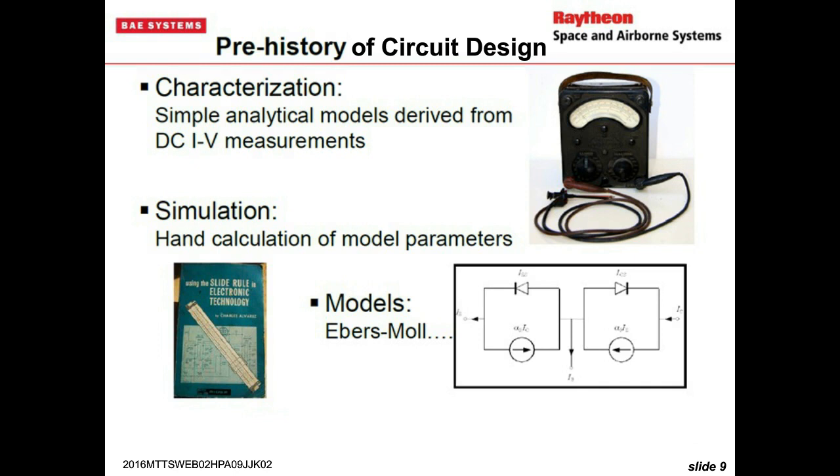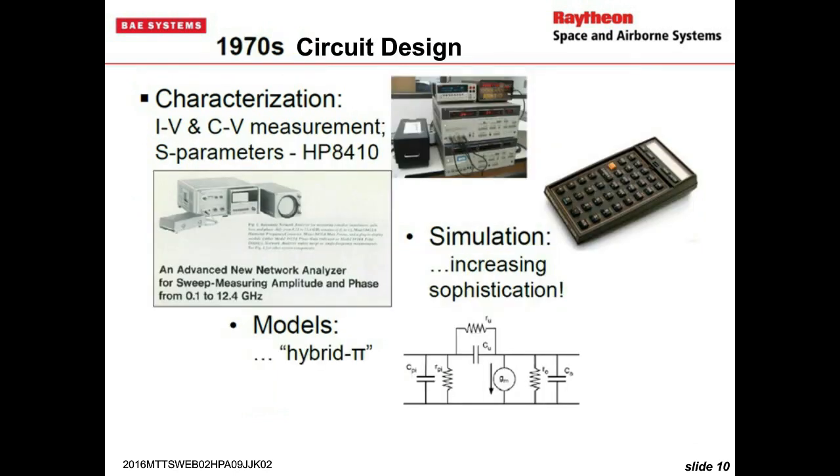The next step and the big advancement was the advent of the automatic network analyzer that allowed you to automate S-parameter measurements. Simulation, the first programmable hand calculators came out, so you could automate some of the process. Models, you can see the model now has losses in it and reactive elements and controlled sources, whereas before all you had was controlled sources and diodes in the model.